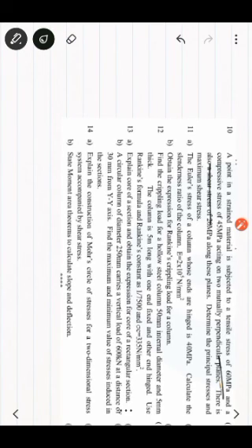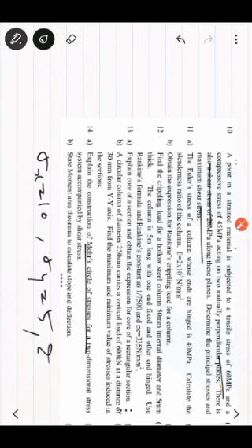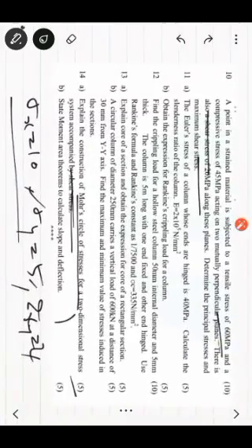Resistance side is put minus, same problem is repeated, shear stress, determine the principal and maximum stress. Okay, this problem, the construction of Mohr circle, you just take 2-3 values of your own. Sigma x equal to, you take some 10, sigma y equal to some 5, tau xy equal to some 4, and just draw the circle. While you draw the circle, write the construction, how you draw those things, and you have the diagram also coming up, so you will definitely get this answer, and if you have drawn the circle and all, you will definitely get these 5 marks.